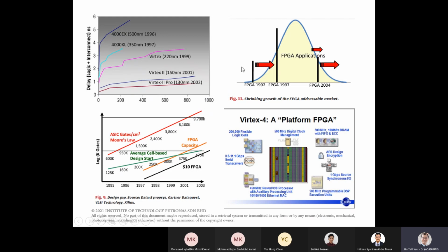So FPGAs, in the early days when they were created, used to be the devices you put in when you wanted to interface between chips, because if you wanted to use discrete circuits you'd have a lot of ICs, so maybe you just put an FPGA. Then as the gate density, the amount of logic that can be implemented in an FPGA, increased, they started taking a bigger and bigger share of the market. And at some point, FPGAs became the technology of choice for small ASIC design.